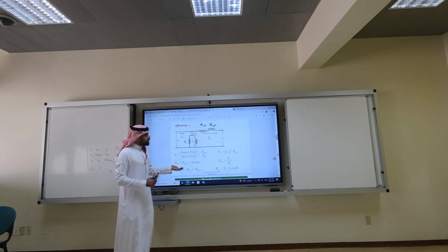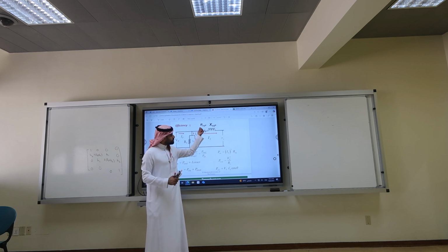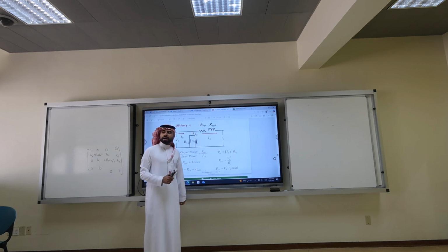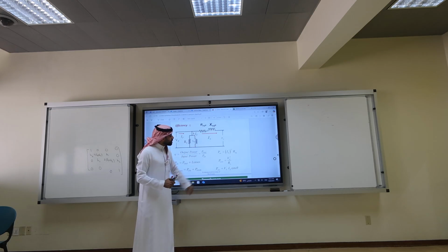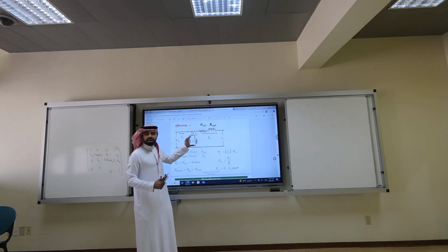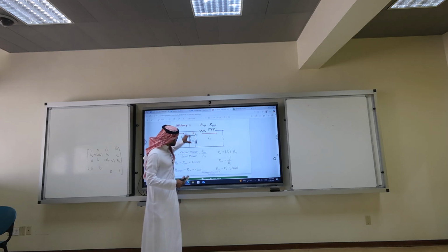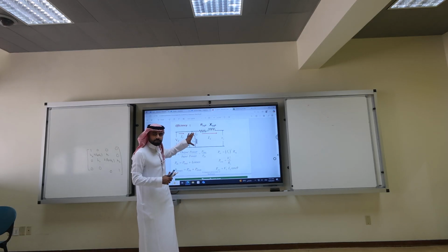What are the copper losses? In this circuit, it is I_S prime squared times R equivalent, referred to the primary. What are the iron losses? V_P squared over the core resistance, R_C. If I use circuit 1, use E_P, don't use V_P. Get it? If I use circuit 1, you use the voltage here, which we call E_P. We did not call it V_P.